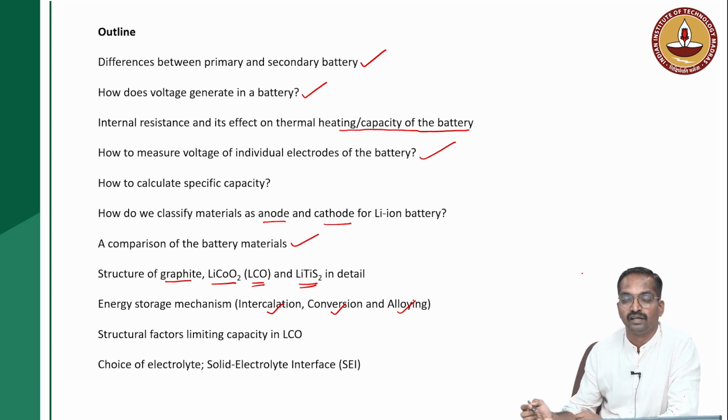So, not every non-aqueous electrolyte can be used for the lithium ion battery. There are certain qualities that an electrolyte should have to act as an electrolyte in the battery. So, we will talk about that, how that electrolyte leads to something called solid electrolyte interface formation at the anode, and why that is important for the functioning of the lithium ion battery. All that we will discuss under this heading.